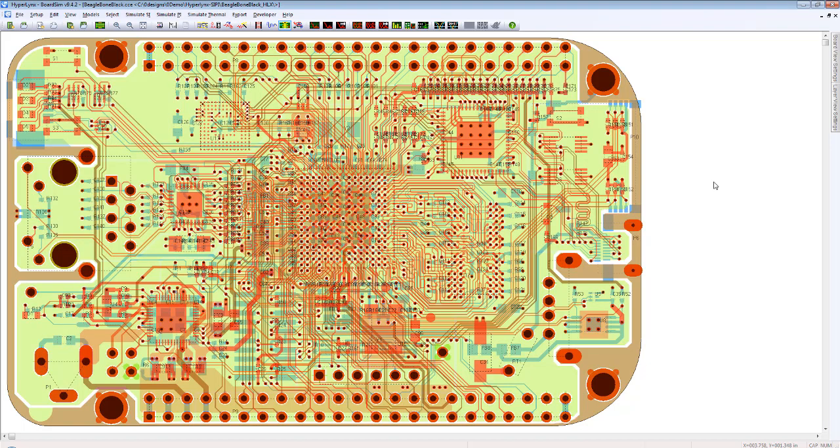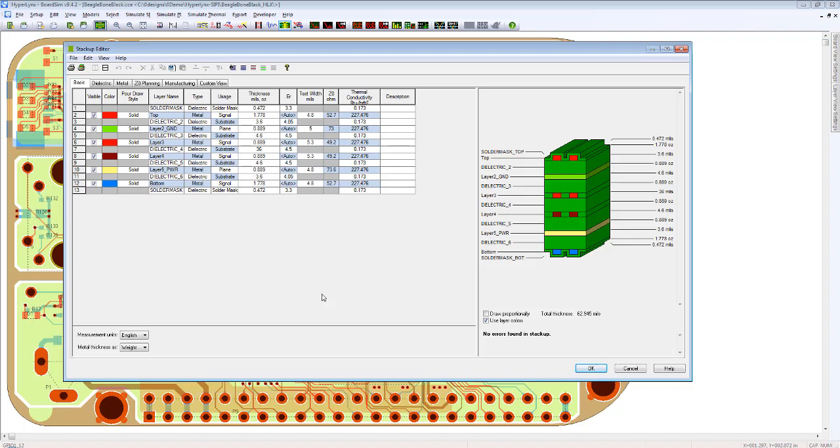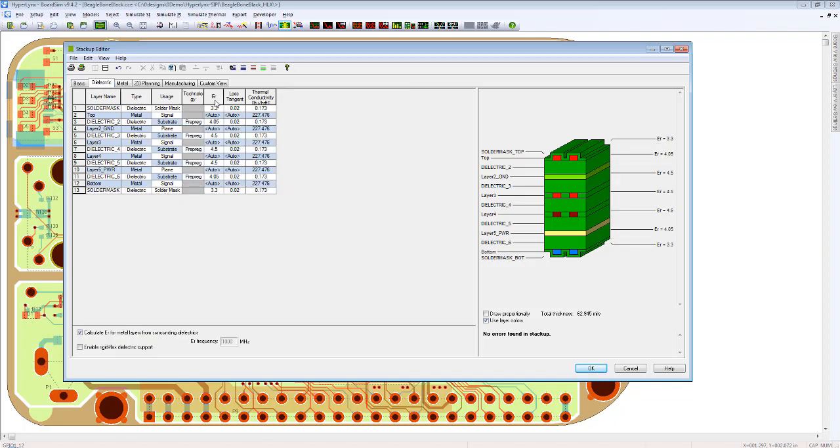Next, in order to do something meaningful with the signal integrity tool, we need to review the PCB stack-up so that the field solver, which is used in such software, can make the proper calculations. For this, we have a stack-up editor in which we model how the real board is manufactured. So we model all the layers that we have. We provide the thicknesses that we ask the bare board fabricator to manufacture. We provide the parameters about the dielectric materials. Those are material parameters which we would get from the bare board fabricator, like the epsilon r of the dielectrics and the loss tangent of the dielectrics.